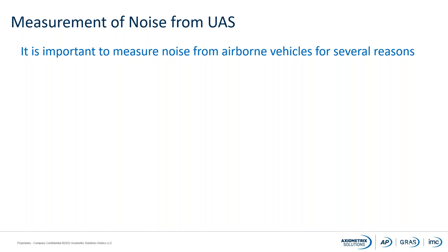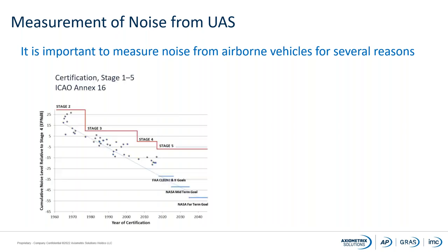And first of all, why is it important to measure noise from airborne vehicles? Well, there are several reasons for that. One of the reasons is that all flying vehicles since the 1960s have been certified. As you can see here, you have different stages, which means that there are different requirements on the aircraft. We started out in the 60s with stage 2 aircraft.